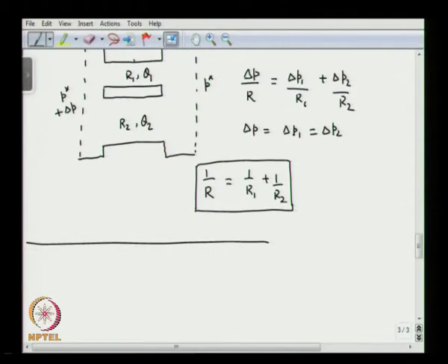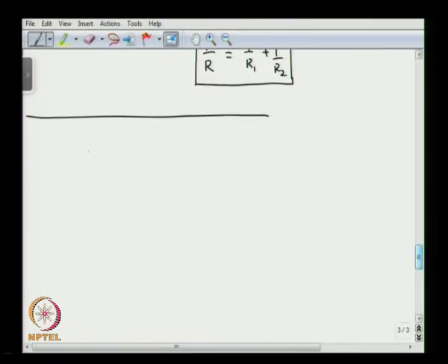Okay. This is because the Hagen-Poiseuille law is similar to Ohm's law, where the pressure drop is equivalent to the voltage drop, the flow rate is equivalent to the current, and we can also say that current is charge per time, right. So, the charge Q is equivalent to volume. So, we can define another parameter called hydraulic capacitance, which is equivalent to electrical capacitance, also known as compliance. Okay. So, we discuss a term called compliance.